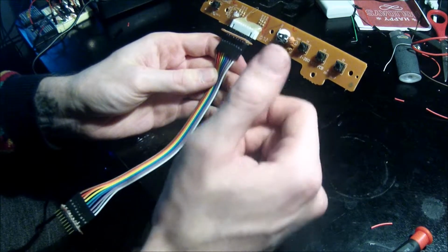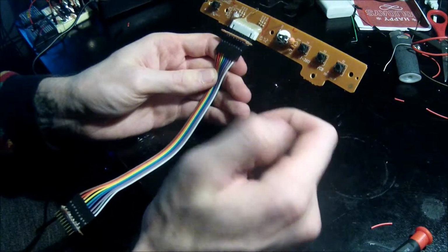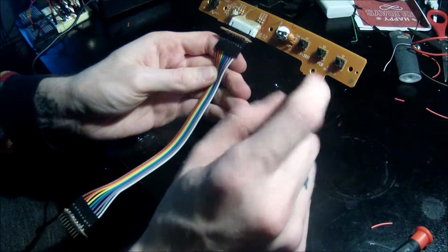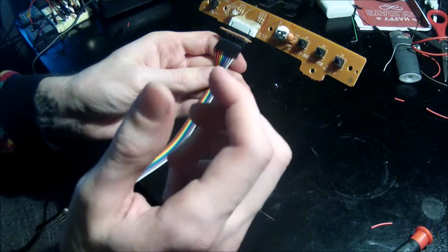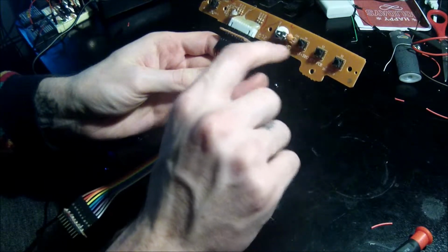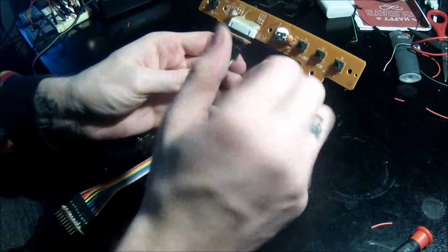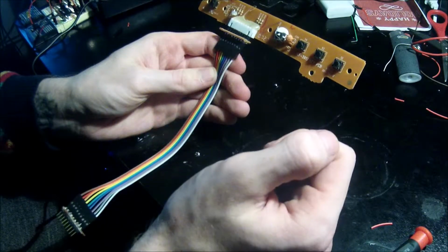What I plan to do with the 8266 is just send a command for each of these buttons when I want to actuate that button, and it'll pull that pin to ground for just a second to simulate a button press. So the Android app, I'm just going to emulate these switches. This is a volume up, volume down, source, and power. So I can just emulate a human pressing those switches with the Android app.